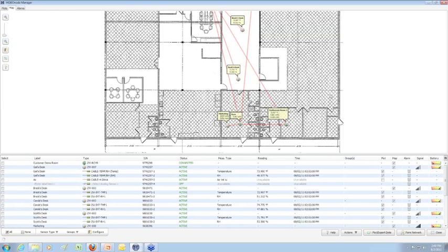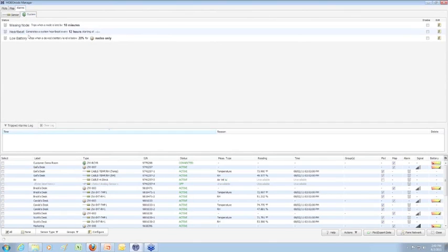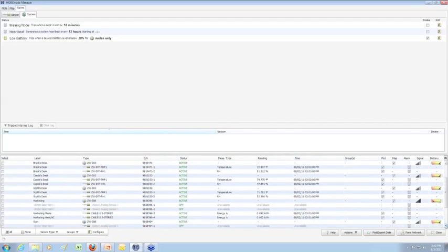And of course, you can set up alarm settings here too for your battery. And actually, I did not touch on the system alarm. So you have your system alarm here. So if any of your nodes are battery operated and have a low setting, you can come in and adjust that. And essentially what will happen, which it looks like I do have a couple out here that are getting kind of low. This particular one here is an excellent example. It actually says I'm at 0. So I'm going to need to change that one.